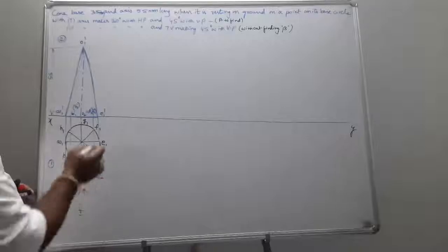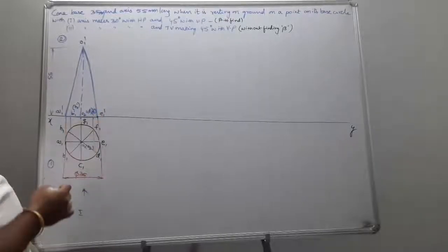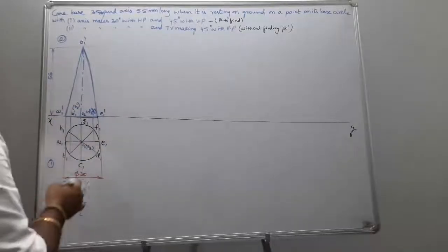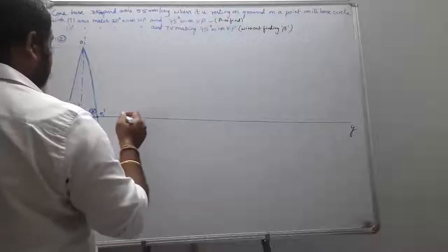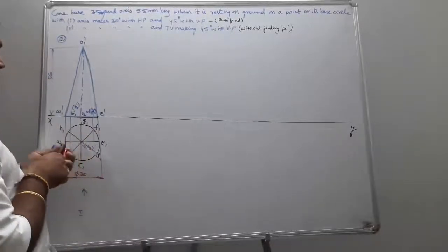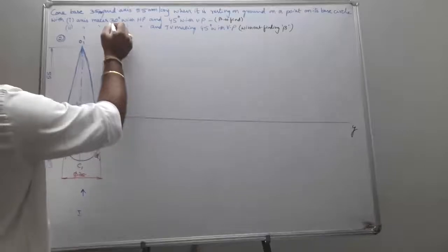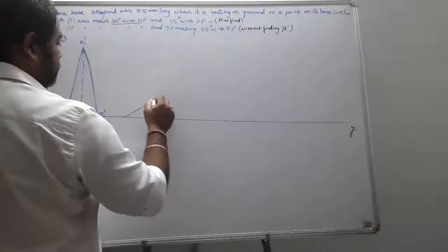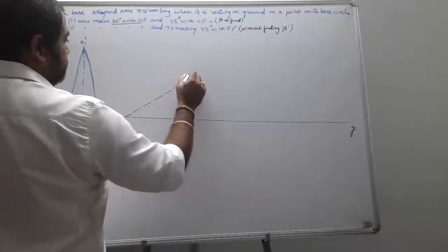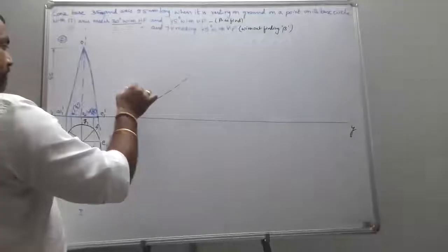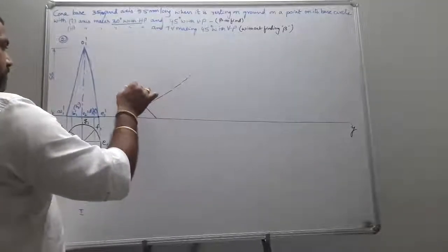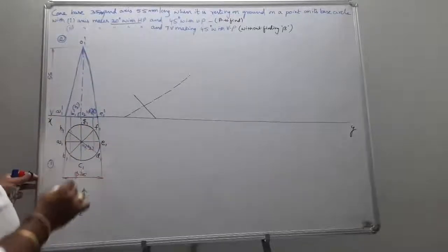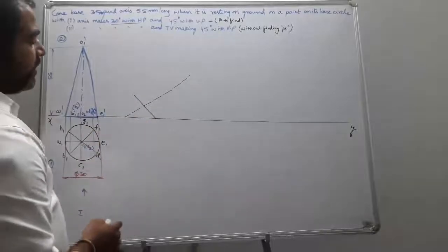Next was axis inclination such that one of the corners of its base is on HP. Let us consider it is tilted, meaning E is on XY. First of all, draw the given inclination. What was the given inclination? 30 degrees with HP. And I know that this AE is going to be perpendicular to the O1 dash O2 dash. So for that, I just draw the perpendicular.